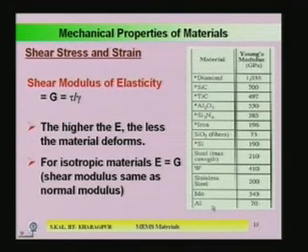These belong to the metallic group, and the Young's modulus in gigapascal is 210, 410, 200, 343, something like that. Silicon is 190, and ceramic materials are also there: aluminum oxide, silicon nitride, silicon dioxide, and diamond has the maximum Young's modulus, 1035. So, these are the values of the Young's modulus for certain materials.